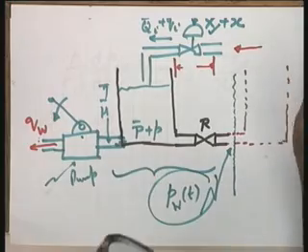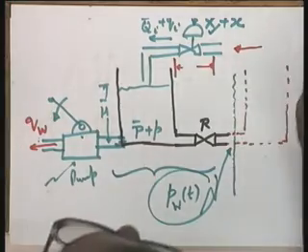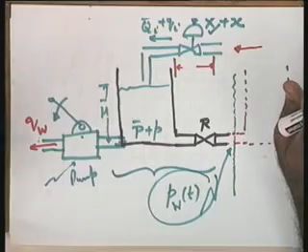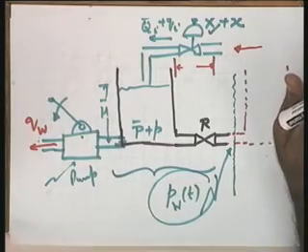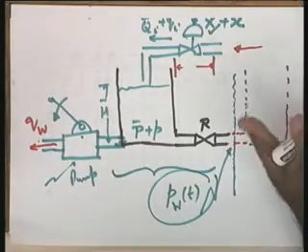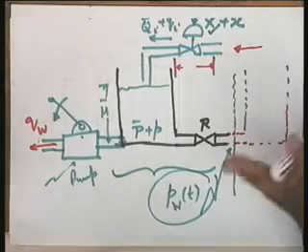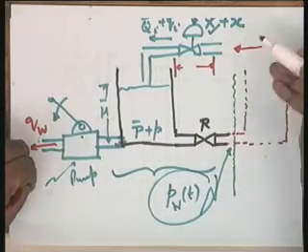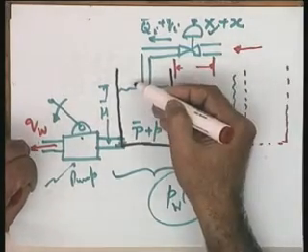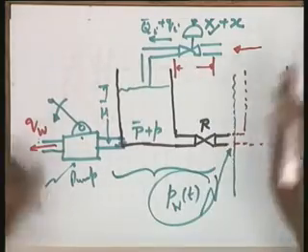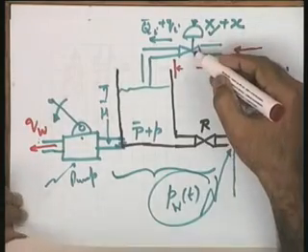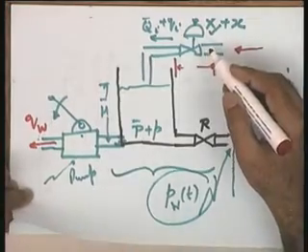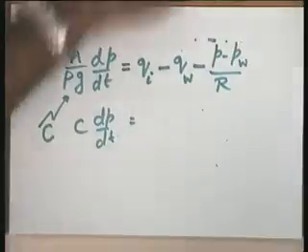I need your attention here. Not that there is no pressure differential. At steady state there is a pressure differential. I am simply taking the perturbation in pressure to be 0, because the model I am writing is a perturbation model, and this is based on the assumption that the overhead tank I have here or the pump I have here and the atmospheric pressure on this side, they remain constant, and hence the mathematical model for this particular control valve will be qi is equal to, well, let me write it directly here,